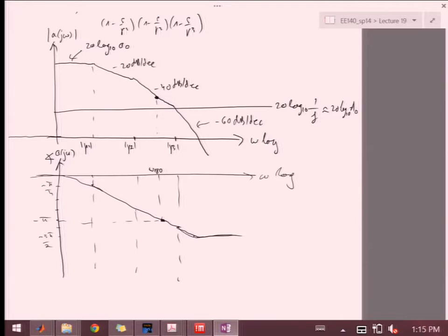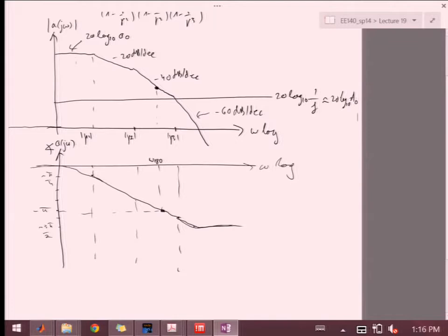Not the loop gain, but the closed loop gain. Because in high gain amplifiers, if you tie a loop back around them, then the closed loop gain is really defined by f, the feedback factor, not the gain of the amplifier itself. And we said that this over here was essentially the loop gain.